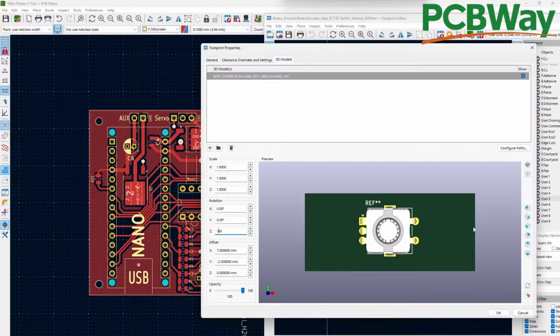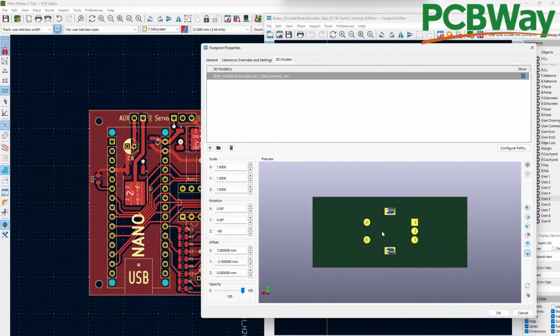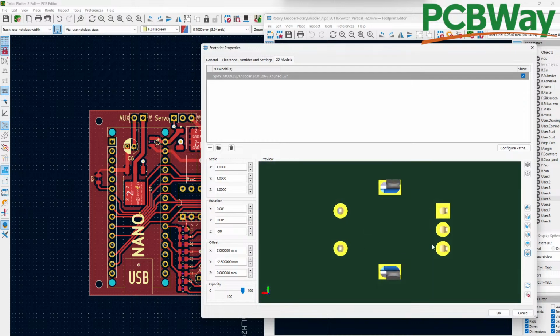And what I find best is actually to have a look from underneath, because then you can see the pins coming through, and you can see that that's slightly off. I think I drew this one actually slightly off, and I forgot to offset one of these two pins. The footprint's correct, my model isn't.